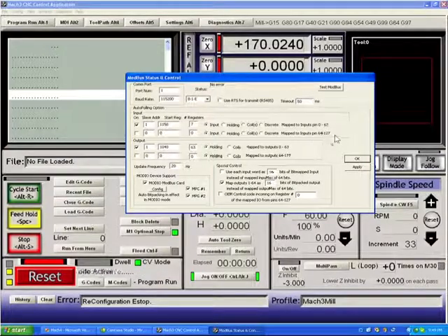So for example, a DL5 may have an analog module on it, and you've hooked a potentiometer across it so you can control your feed rate override. You would tell it the starting address of the block of memory which contains the analog value of that potentiometer, and you would say that you want 1 register. This will transfer that register into analog array pin 64 or position 64. There are macro script calls to call the data into the program so that you can use that data in a macro pump or another script to automatically perform operations with it.